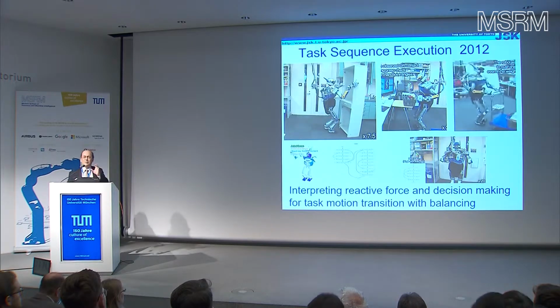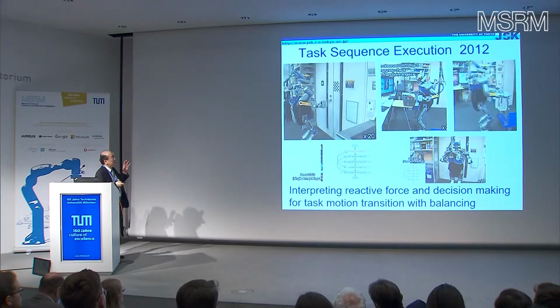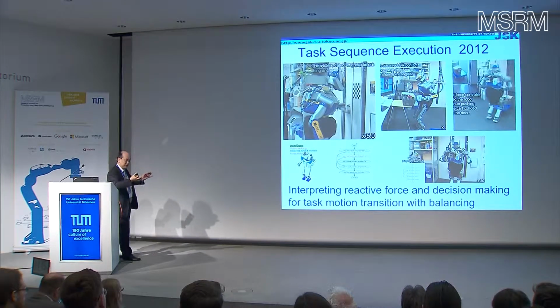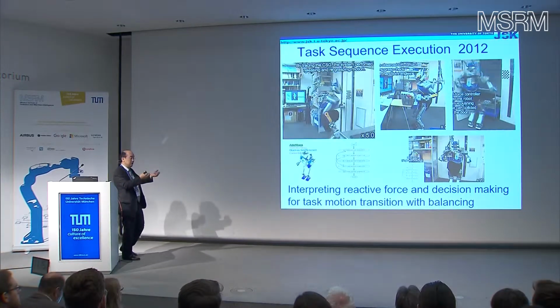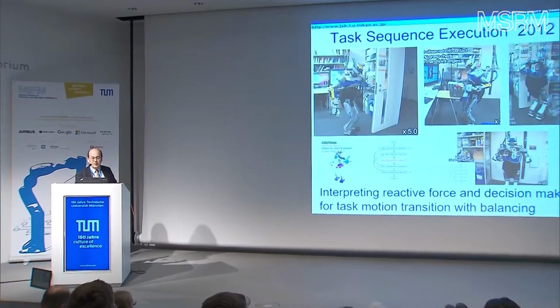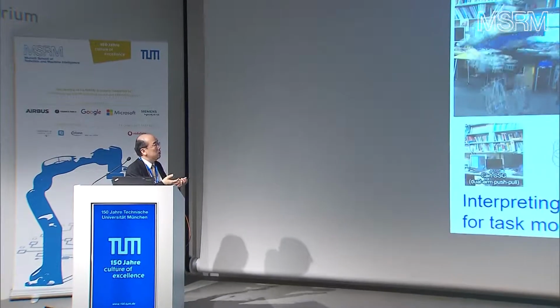The idea is the same as Professor Inoue's first one 50 years ago, but in this robot, it has 4 6-axis sensors in the wrist and ankle. Then the robot can keep balance and react based on the reactive force change, saturation or impact. So changing point detection is the key for his PhD thesis.